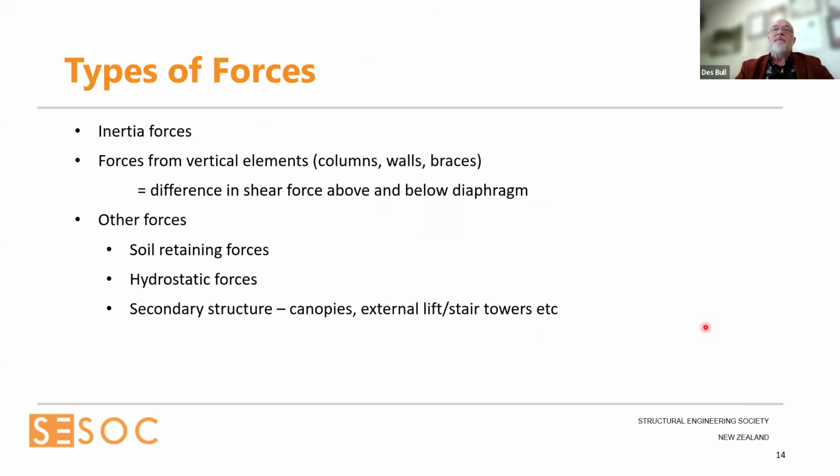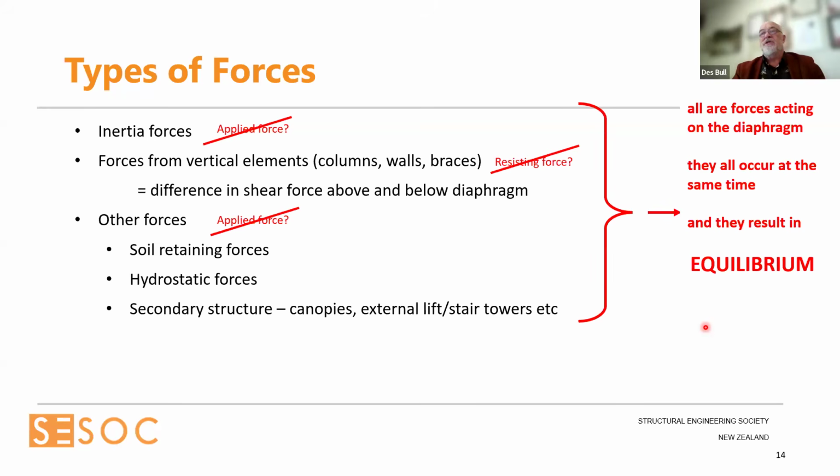So we've seen the slide already, but people think inertia forces and other forces are these applied forces to the diaphragm? Are the forces in the vertical elements the resisting forces? Well, yes, they are. They are in one sense of the whole building. But when we look at it in terms of what we're doing with the diaphragm, we sort of treat all these forces as acting on the diaphragm. Both the inertias and the resisting forces are acting on the diaphragm. And we set it up such that it all occurs at the same time. And the main thing is it's all in equilibrium.